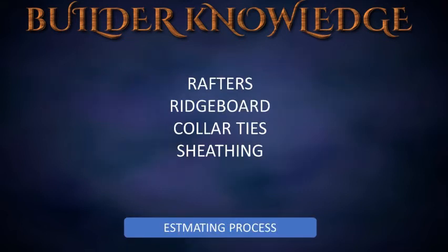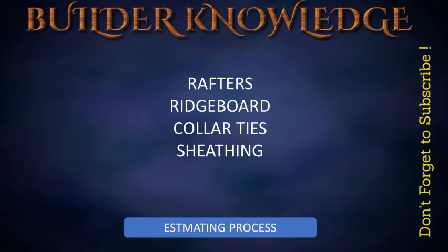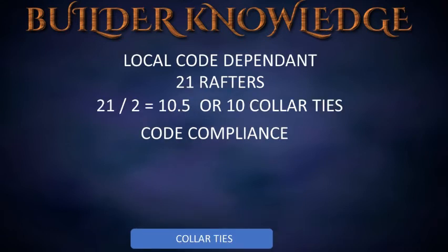Collar ties. The number of collar ties required depends on local codes. If a city requires collar ties every 48 inches, a building in that city with 21 rafters would require 10 collar ties. For example, with collar ties required every 48 inches and 24 inches on center rafter spacing, a collar tie is required for every other rafter. 21 rafters divided by 2 equals 10.5, or 10 collar ties, required for code compliance.